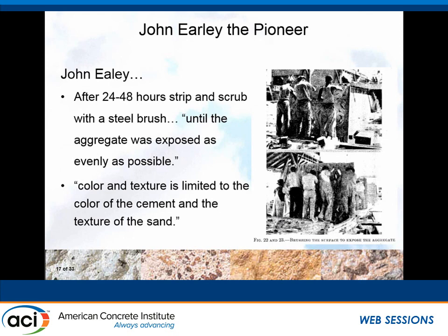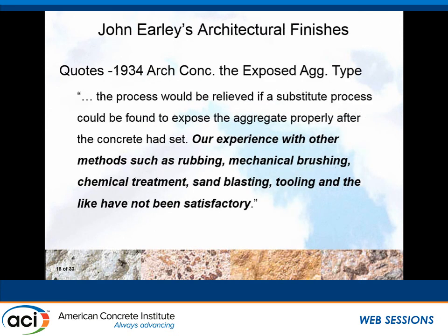He, like we talked about, would not use pigments. All his color was typically developed, especially in the early years, by the use of the aggregate itself. And I think that in one of the publications he was saying, "Gee whiz, I wish I could do something else," but our experience is that all these other methods don't work as well. We don't end up with a pristine concrete at the end that is up to our standards. And one of the things he talks about is that you can't use chemical treatments, sandblasting, etc.